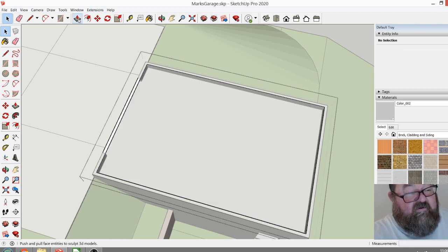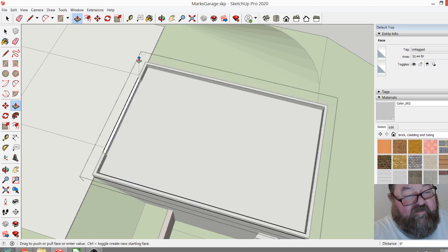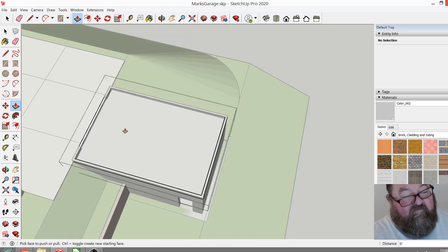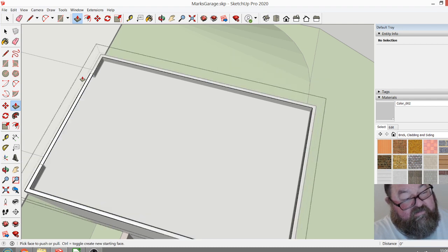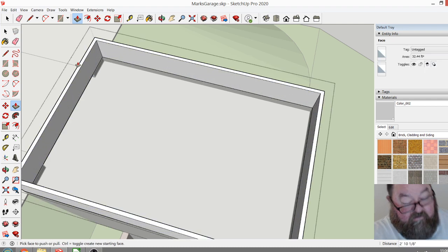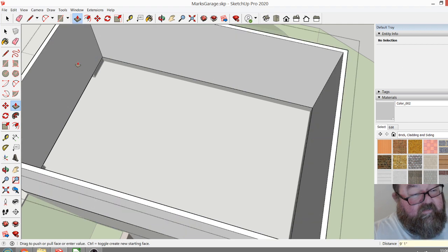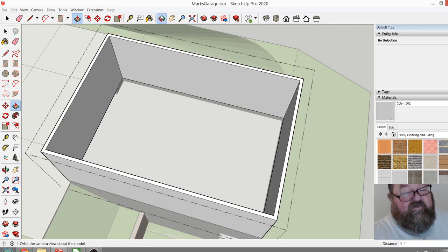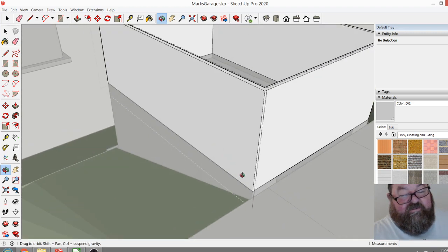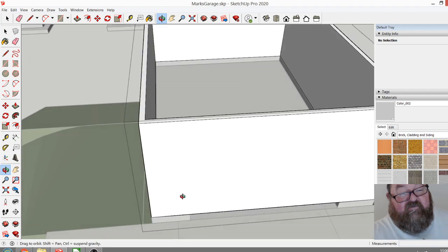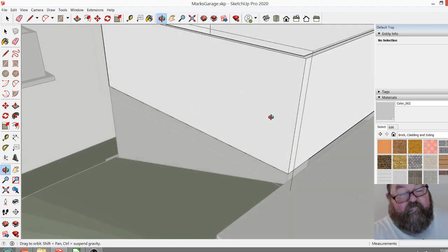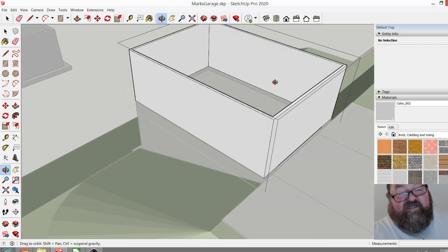And now we've got walls that I'm going to bring up to 9 feet 1, if my SketchUp tool, wow, something freaked out. 9 feet 1. The reason I'm doing that is because I would propose using regular 9-foot studs on top of that little stump, and that will give you close to a 10-foot ceiling.